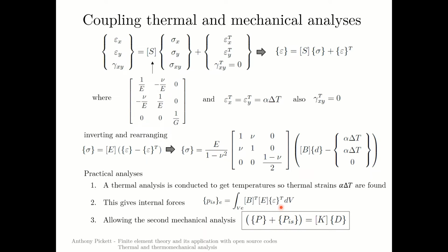So we multiply the strains by the modulus. And these stresses computed using this relationship are converted into nodal forces. In other words, these are the nodal forces that would give us the thermal strains that the material is experiencing.